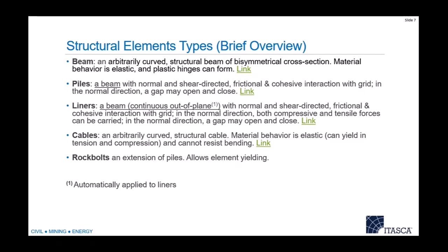They don't form in an array out of plane like beams and piles do. Their interaction with the grid is much like a pile. However, they have subtle differences in how they interact in the normal direction. And those subtle differences are basically to really mimic what a concrete liner might be, like how a pile might interact in real life.